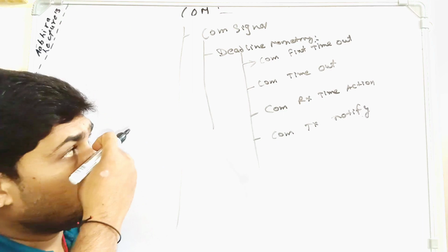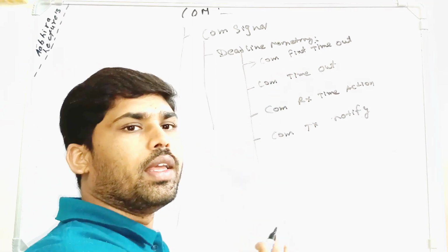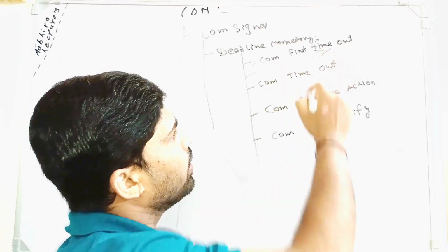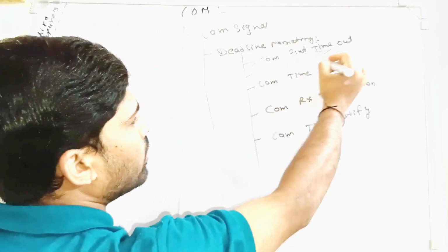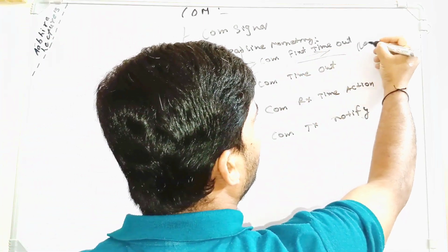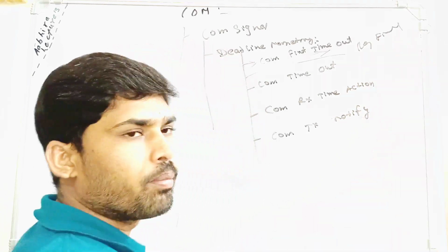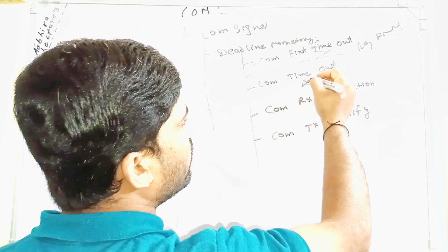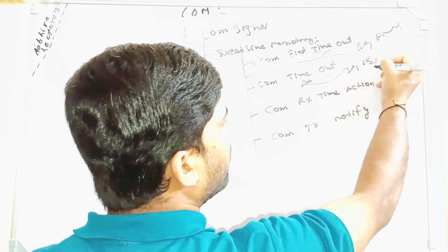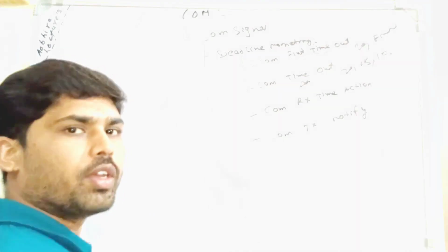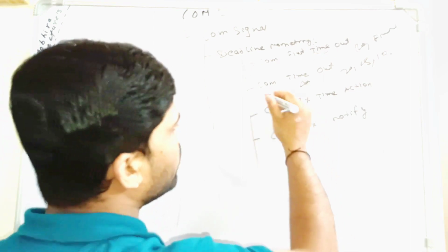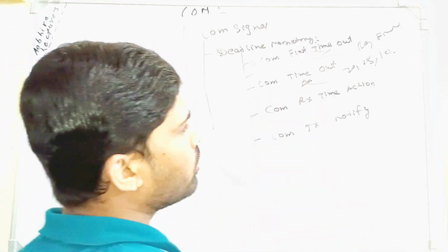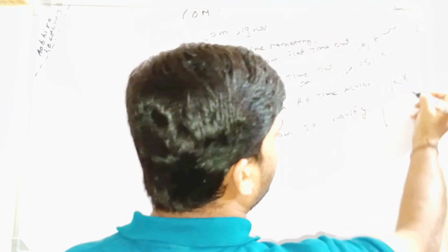Okay, so I will explain how it works. If any signal will not transmit within the first timeout, say within 10 seconds, then the first timeout will happen. Okay, again the signal will not transfer within that 20 second or 5 second or 10 second, whatever periodicity we have given to transfer the message or signal. At that time it will not transfer, then again a timeout will happen. And one more thing, it will happen on both the rx side and the tx side.